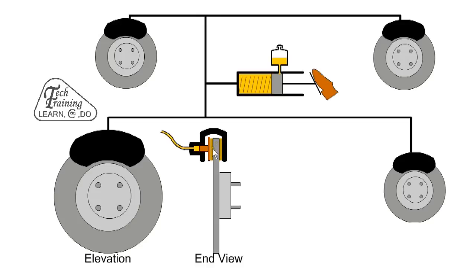When the brakes are applied, the rubber seal deflects slightly. When the brake is released, the seal returns to its normal shape and moves the piston back slightly from the wheel. If the fluid expands due to heat, some can return to the reservoir. If there's a leak in the system, the fluid will be topped up from the reservoir. Excessive leakage will be detected by the level switch. If there was a severe leak in the system, we would lose all brakes.